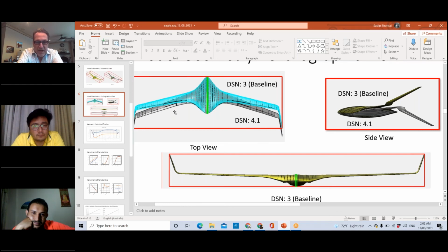Yeah, it's true that the flow at the reflex, obviously the back of the center body is working hard, is kicking the flow up for a lot of the trim, and so you would want to align it with that kick-up flow, and you probably need to look at CFD to see what the flow relaxes at. It doesn't have to have perfect alignment, but you still could use it if you wanted to, but you'd have to be careful about aligning the prop. Yes. One thing that's nice about the prop at the back there is, I think we talked about this, maybe prop normal force.